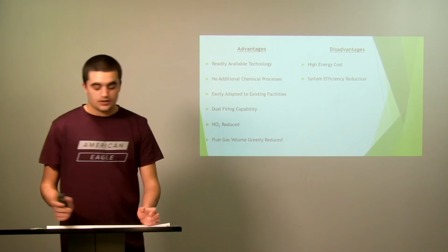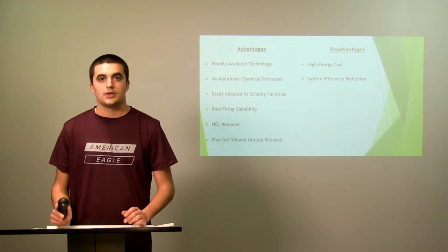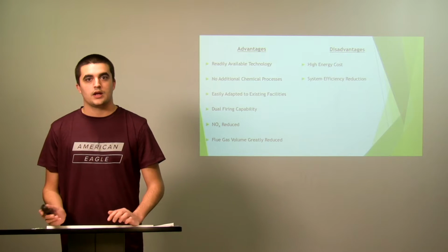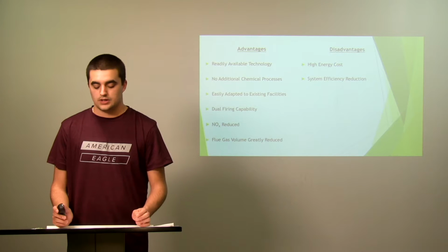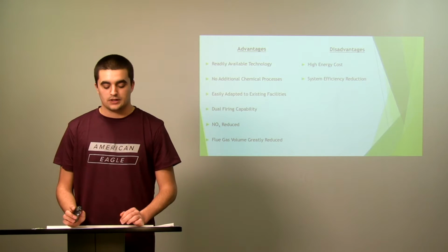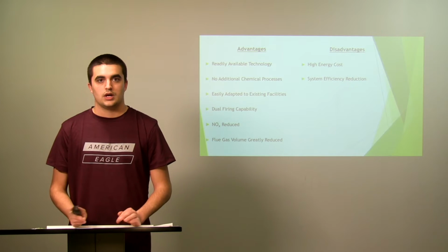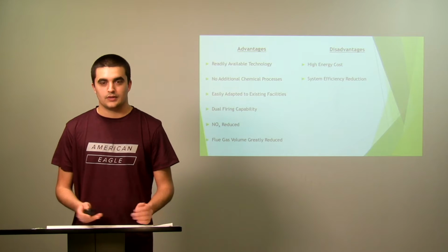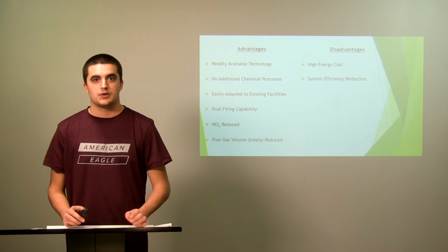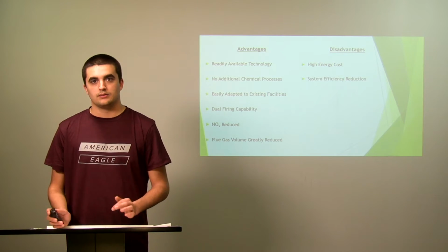So with this technology, there are many advantages and disadvantages. The first is we already have this technology. It's been around since about the 1980s to 1990s. Also, unlike other carbon capture methods, it requires no additional chemicals. Also, it can be easily adapted to all existing facilities since it just switches over the initial oxidant intake. It also has the option of dual firing capability, which means it could switch from oxy-fuel combustion back to air-fuel combustion based on peak and low demands.